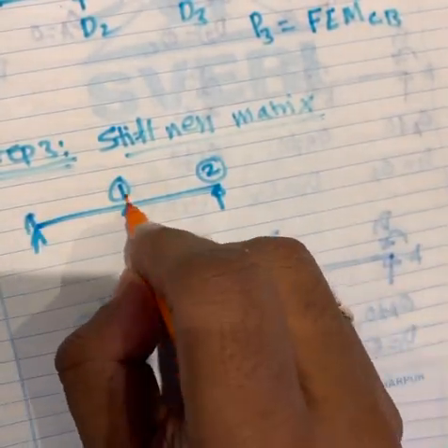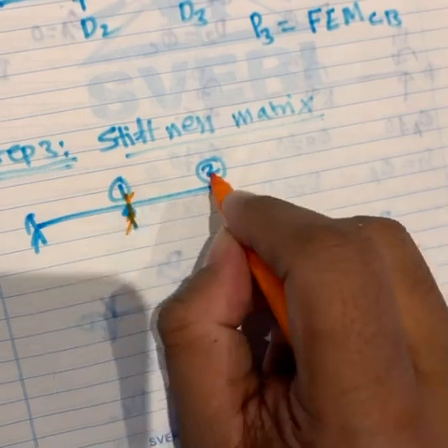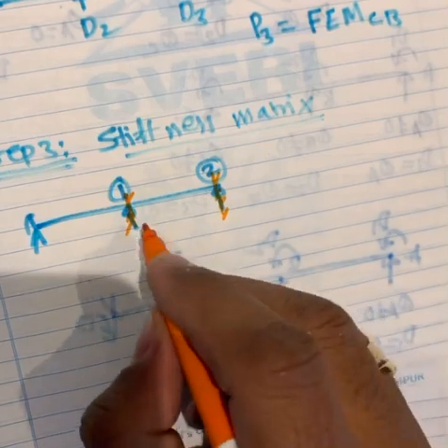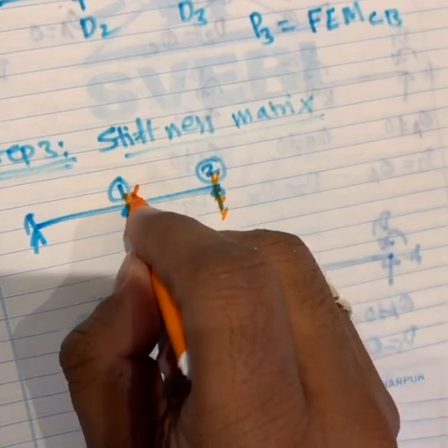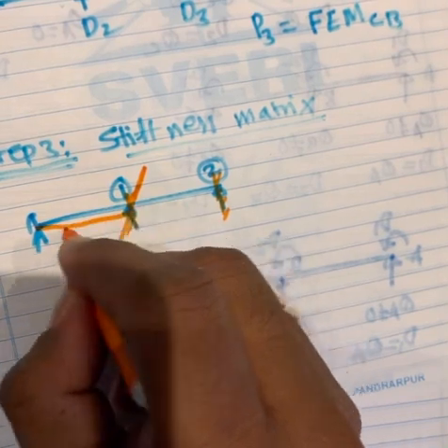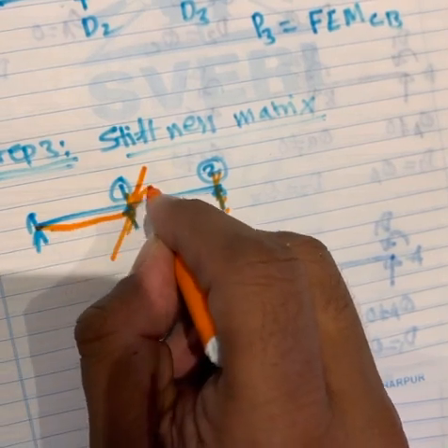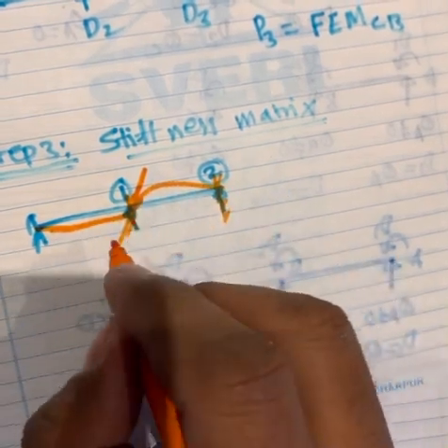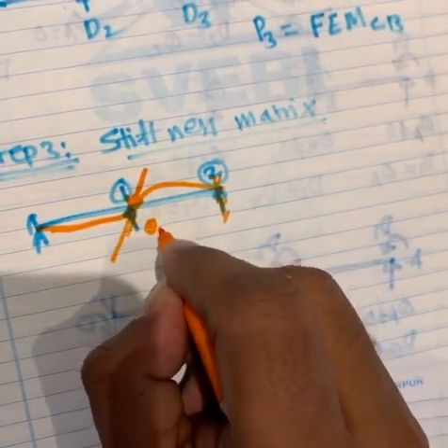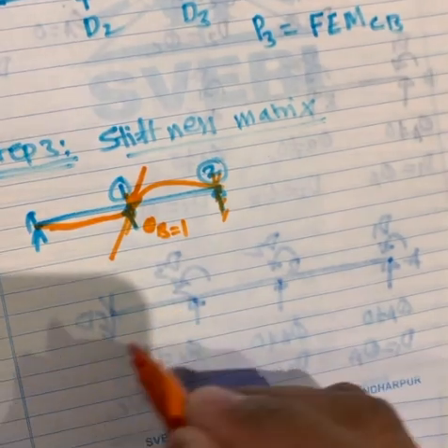First of all, before giving the rotation, as we know in the displacement methods, we have to fix, that is, restrain everything, and then rotate it. You give unit rotation this way, then similar equal and opposite rotation will be generated on the other end. So that will be theta B equal to 1.